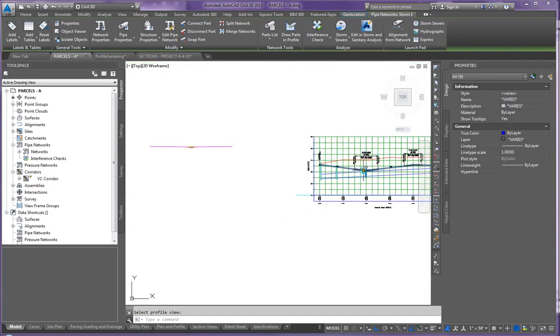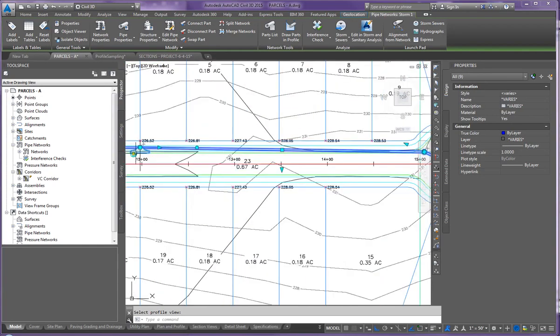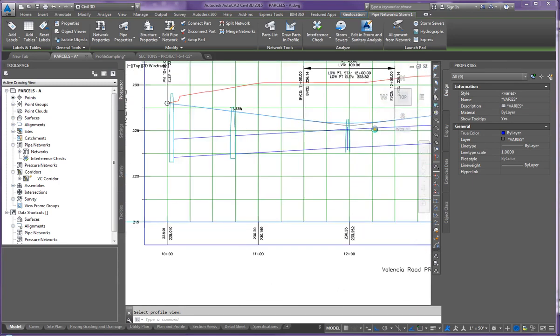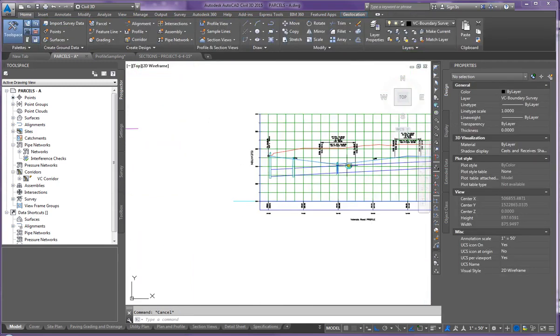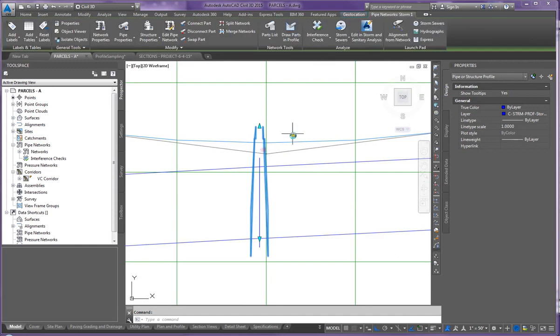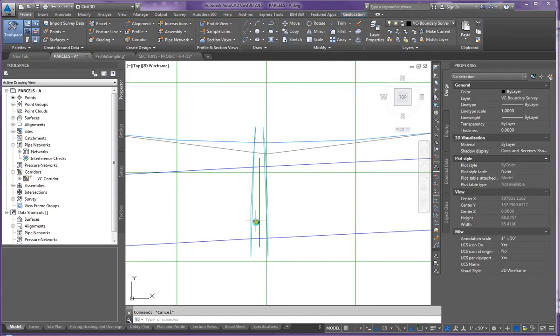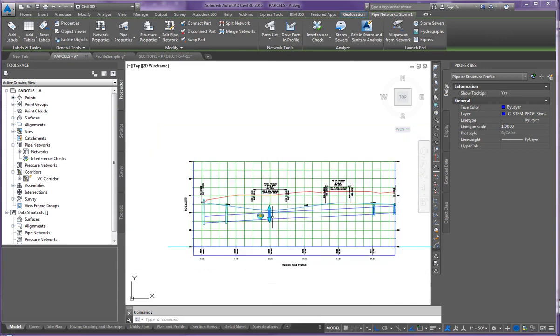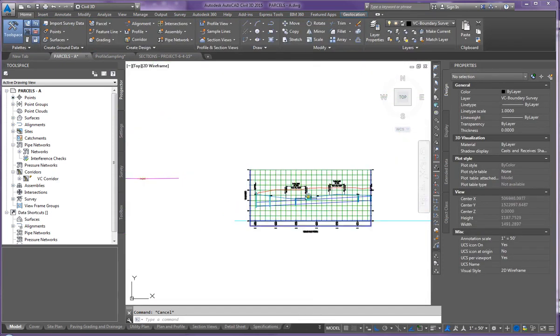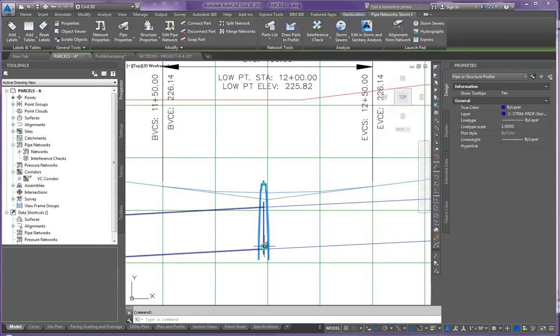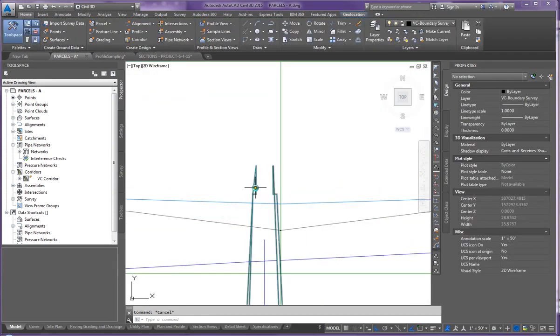This is true because it's actually building, we are not at the edge of pavement here. So the center line, remember the center line goes down 2%, comes up a half a foot for the curb, and then starts going up 6%. So that's why this is jutting above that. All right? Now, something doesn't look right here. I've got this structure here that appears to have a odd invert, that it's not actually building it correct. So this one here is, let me get that off of there.